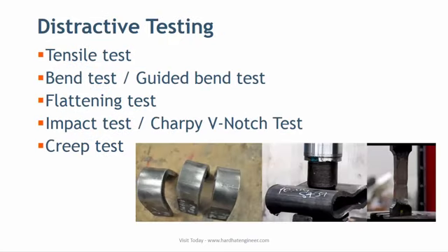Ultrasonic testing can be done on full body or only for weld seam, whereas radiography is performed on weld seam only. Magnetic particle test is performed on pipe ends and weld seam. Hardness check is also performed on metal to confirm the standard requirements. In future video, I will try to cover a brief overview of these NDT methods so that you have a working level understanding about them. If you are an inspection engineer, you need to know all this testing in much more detail.